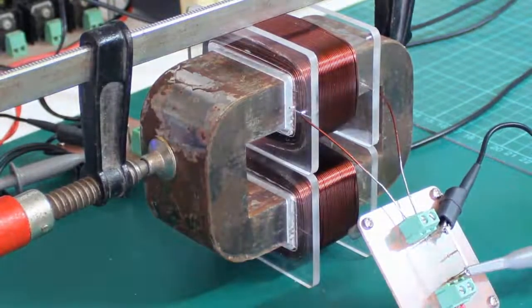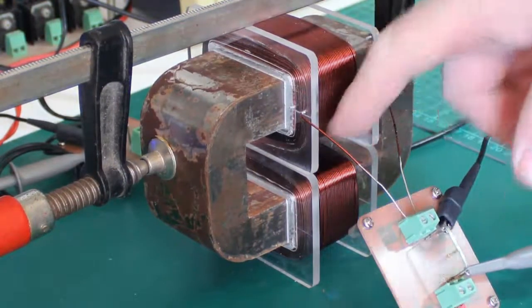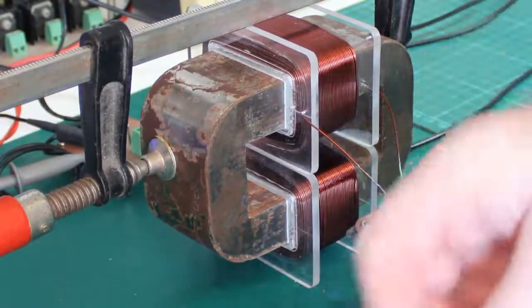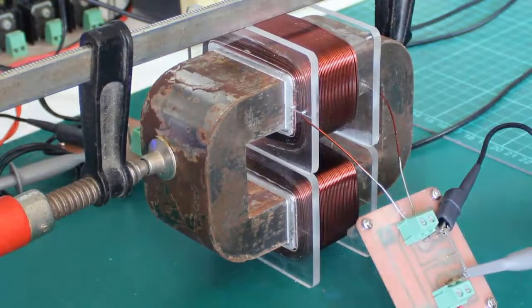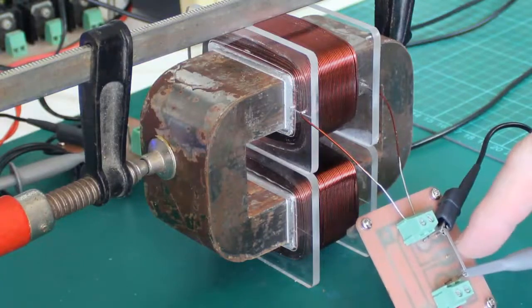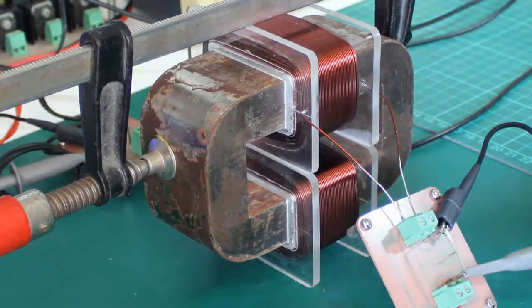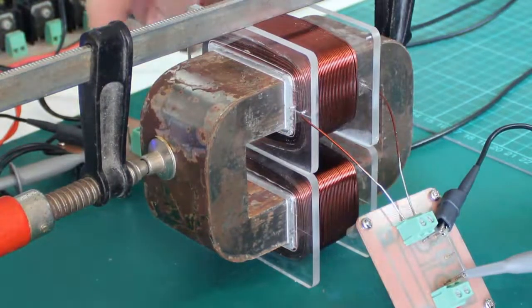Alright, I've got a basic DC transformer here at the moment. Very, very simple. A couple hundred turns on each coil. This coil is powering the little load here, very small. Sensing resistor here, scope yellow channel, probe set to 1 times. On the scope itself, set to 10 times. 0.1 ohms times 10 times is 1. So that's why the scope's set on 10 times. Probe on 1 times. Okay, I've got the same at the back.